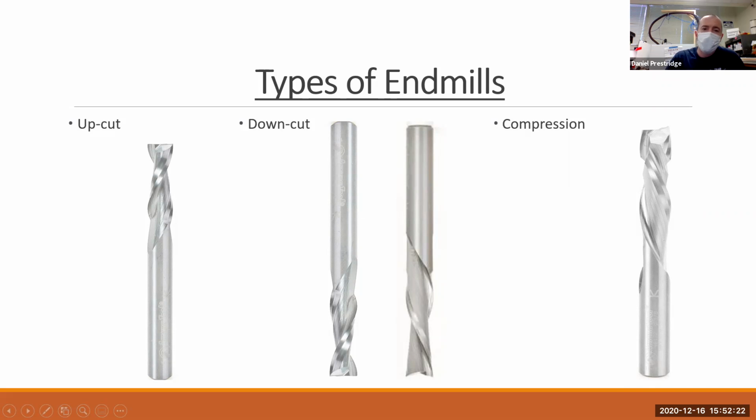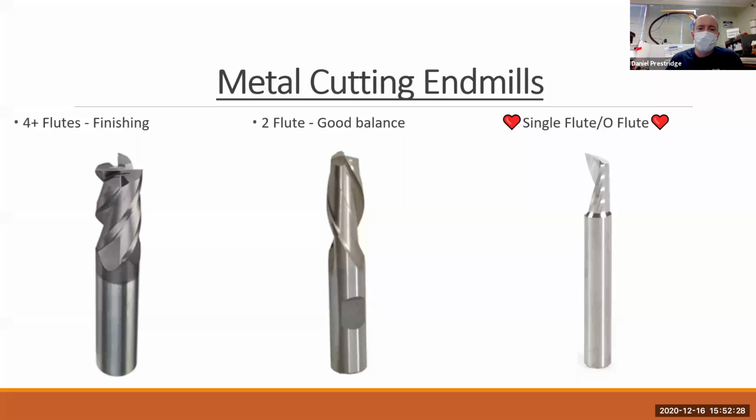So picking the right end mill is critical for your success. And for metals, aluminum, we don't normally do steel, but you can also do steel. I'm just going to refer to aluminum. For flutes, as you move through, you have a flat bottom. So if you were to move down into some pocket and clear that material, it would be flat at the bottom, which is great.